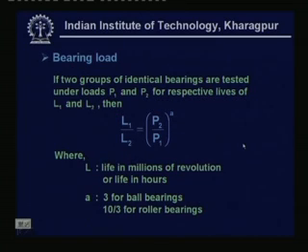Now, it has been seen that if two groups of identical bearings are tested under loads P1 and P2 for respective lives of L1 and L2, then an inverse relationship stands: L1 by L2 equals P2 by P1 to the power a, where L is the life of the bearing in millions of revolutions or in hours, and a is a constant which is 3 for ball bearings and 10 by 3 for roller bearings.